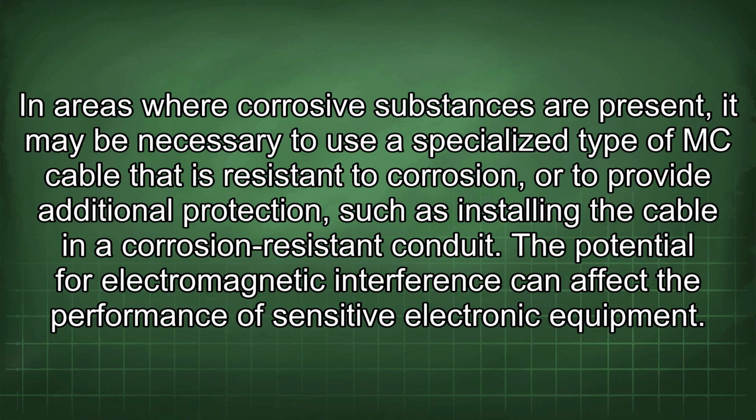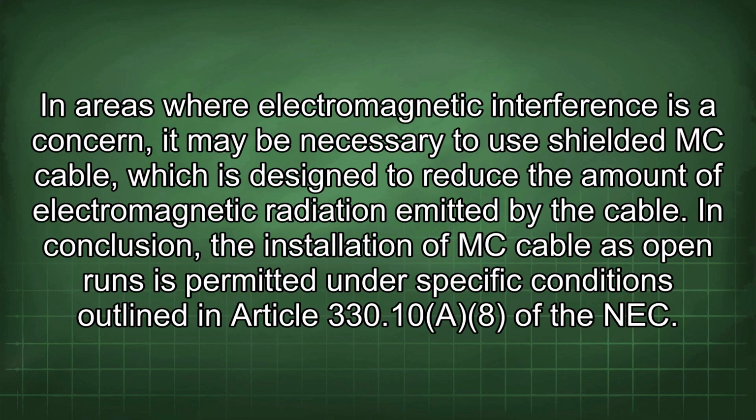The potential for electromagnetic interference can affect the performance of sensitive electronic equipment. In areas where electromagnetic interference is a concern, it may be necessary to use shielded MC cable, which is designed to reduce the amount of electromagnetic radiation emitted by the cable.